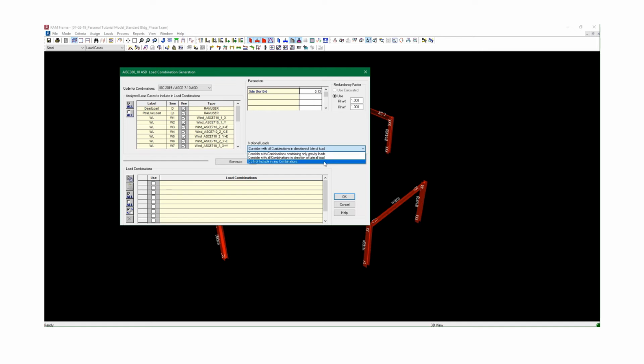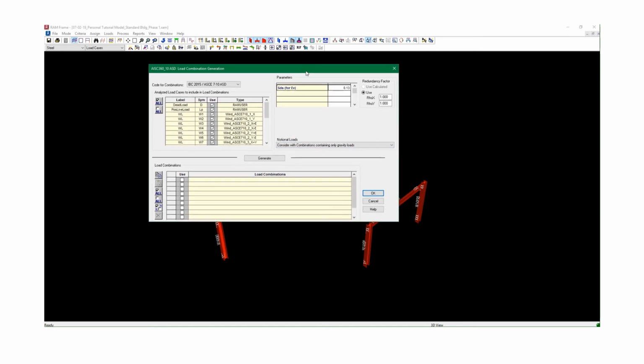I don't have to combine it with any in certain instances, or I can provide it only with gravity in certain instances. And for this structure, we'll combine it only with gravity and then validate our assumptions afterwards. And we can always modify this information if we were incorrect.